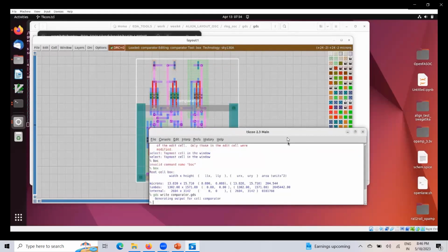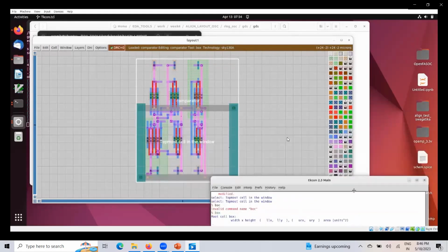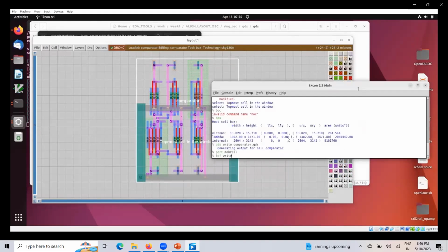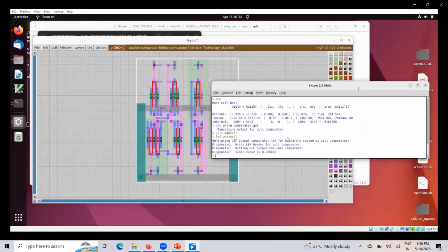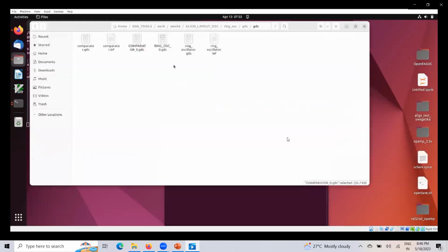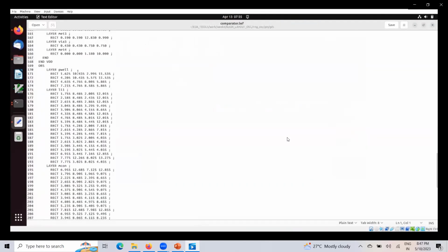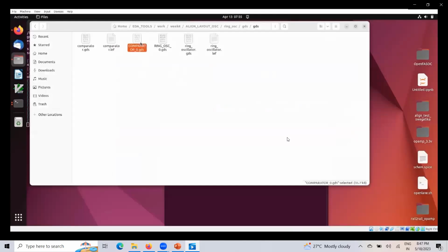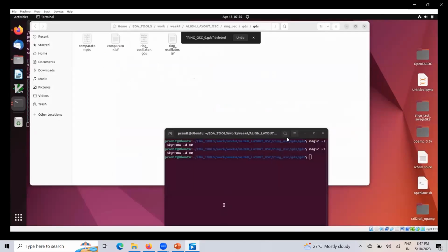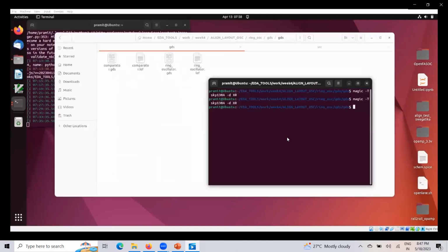We write the GDS, we make all the ports, then we write all to generate the LEF files for this. Now we have set up the necessary GDS and LEF files that are needed for the flow. We don't need these previous GDS files, we have all what we need. This will go into the blocks directory of our async up down gen folder.